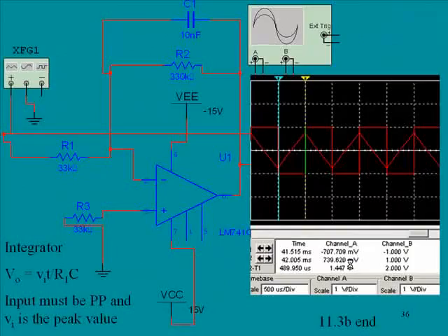Now the next page here is this same circuit, only it's larger so you can actually see it. And we have the signal source here, and we have the oscope readout. And this was a simulation from Workbench where I've captured the output and the actual circuit. Now this is the formula we'll be using, and this is going to be VI times T. So that'll be the input voltage times the time, and then that will be divided by this RC time constant, and that will tell us the output voltage.